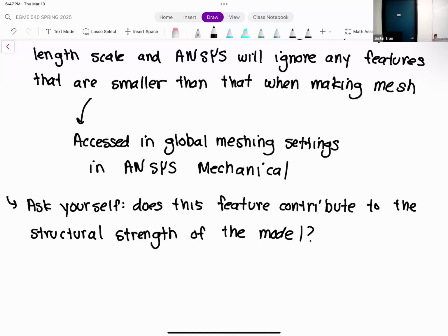This looks fine. The thing I think is concerning for a lot of people is actually this boundary condition here. I should really change this to a fixed support. I have this here just to show people what this place and support does. I can change that to a fixed support, and right now all the stress is concentrated, but if you change that to a fixed support, it's distributed along.